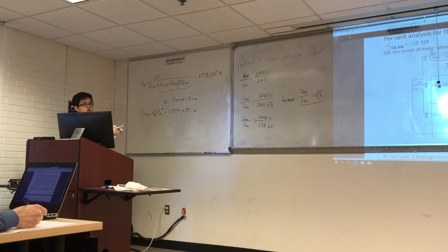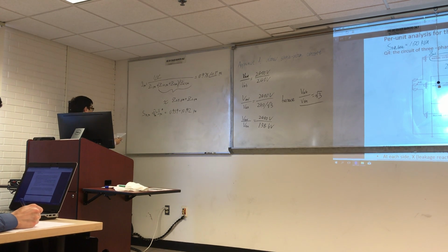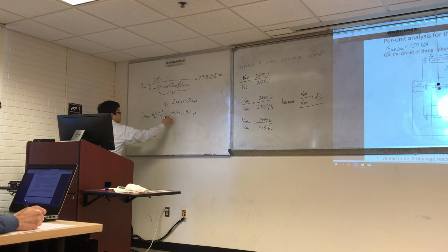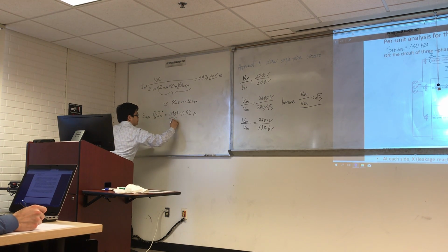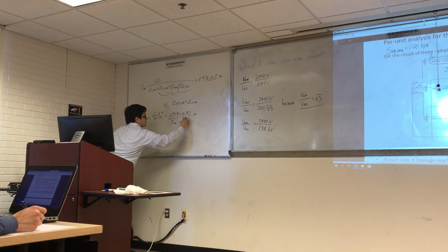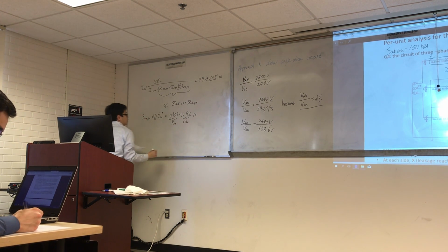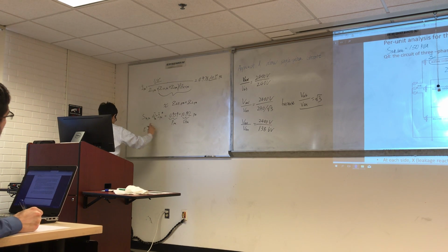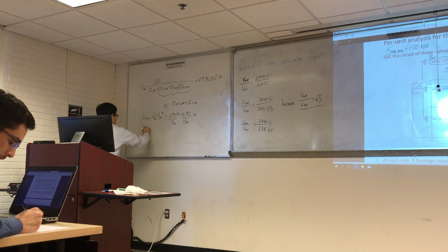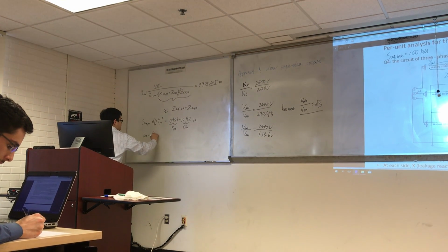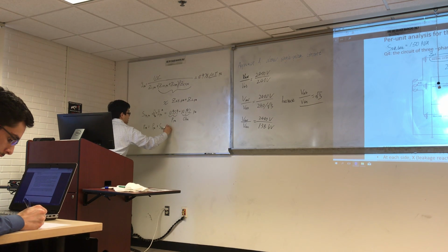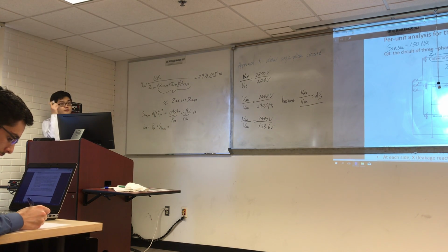So convert it to the real value power. This one is your P per unit and this one is your Q per unit. What's the real value for your input power? P input equals P per unit times S base. S base is 50 kVA.